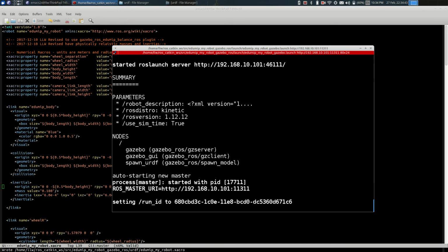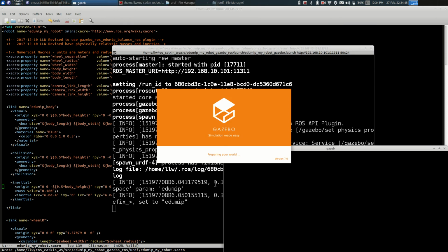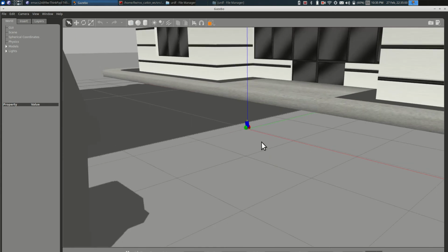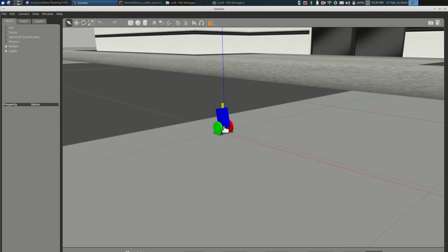So when we run this time, we've moved the mass. Mass is invisible, and it's half a body length below. Lo and behold, the robot is standing up. Right? So we're cheating right now. And next week we'll use a plugin which actually does closed-loop control to keep the robot stood up. And so this is essentially a pendulum on wheels, right? And you can't see the mass down here easily.